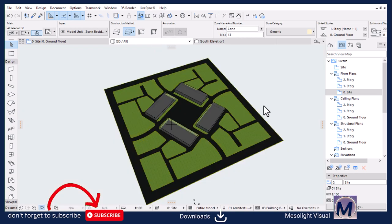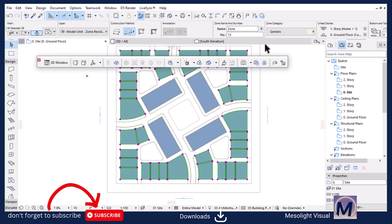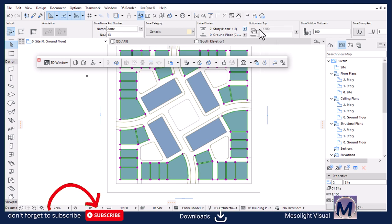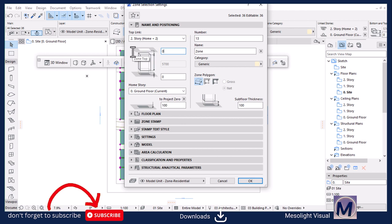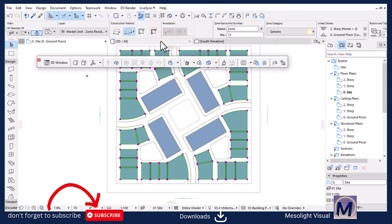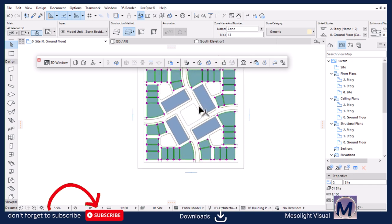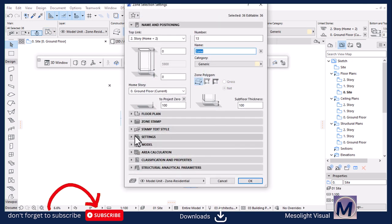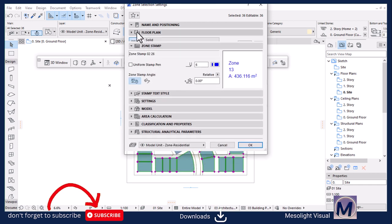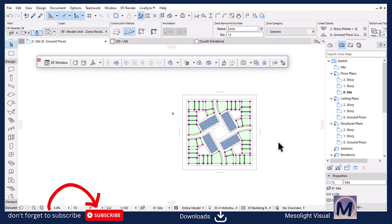So if you check on 3D, we have now all this. Oh, sorry, we need to go back here and set it to story 2. Open its settings. Let's set this to 0 and then hit OK. Okay, but in the floor plan, we need to differentiate this. The residential has to be in a separate color, and then the commercial has to be a separate color. So let's go back to the settings under the zone stamp. No, I think it's floor plan. Yes. Let's set the color to white, something like that.